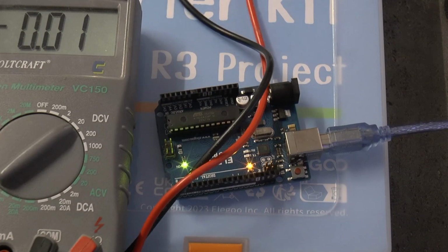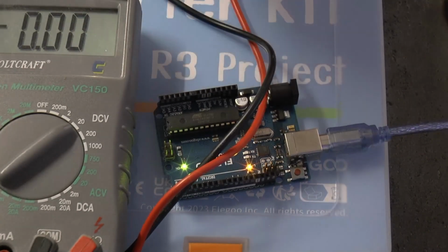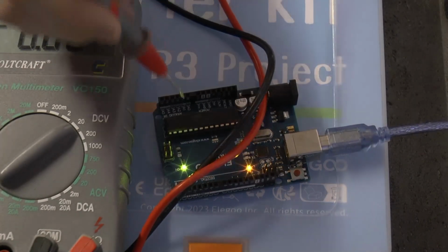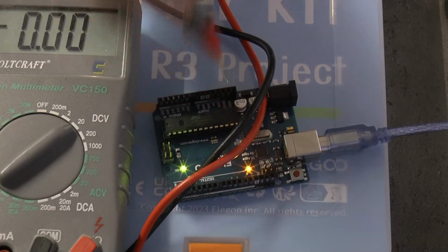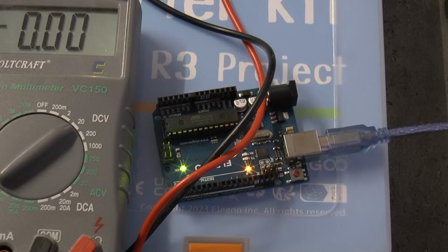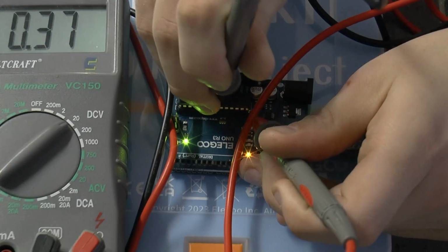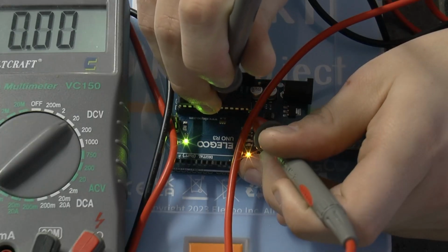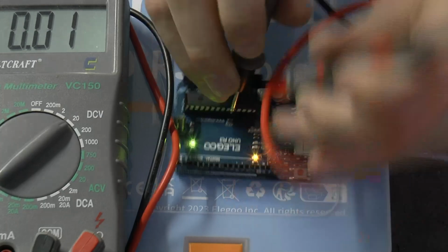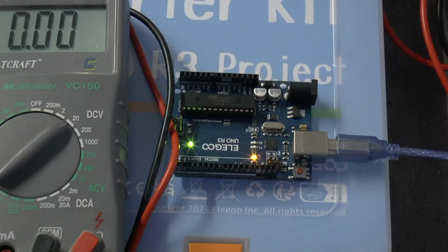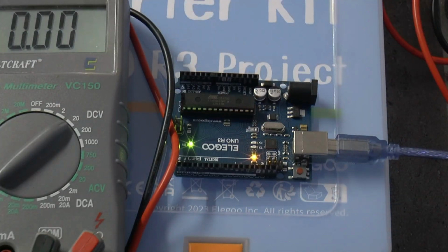But let's first position the plus, because I need to actually bend quite over to get my leads in, which is here. This is the topmost, the one that we are controlling. And now I'm going to try to catch the signal. This one as well. Yeah, there you got it. I think you quickly saw the blinking, right? You saw the blinking on the multimeter because of the 4.5 volt and the 0 volt. I did not really get a good contact there. So now I've basically moved it to the pin.